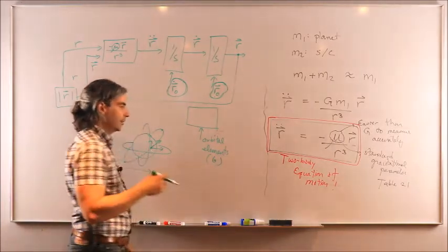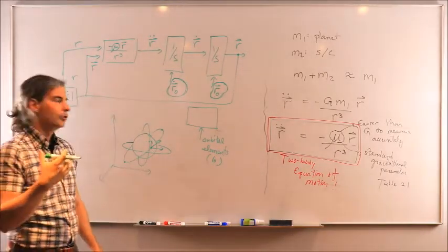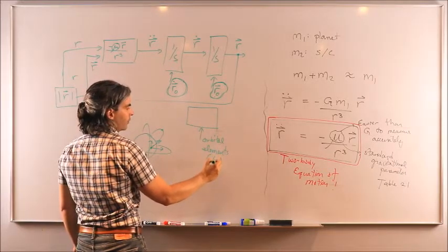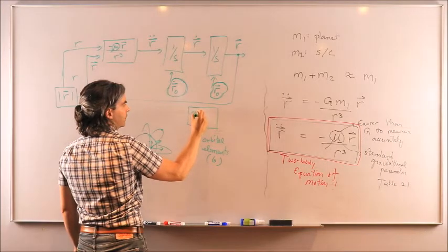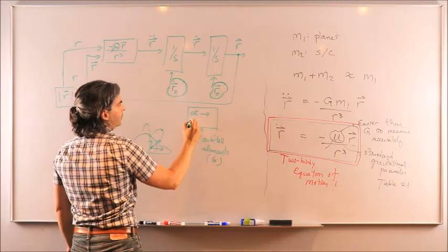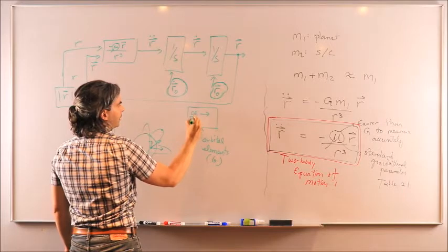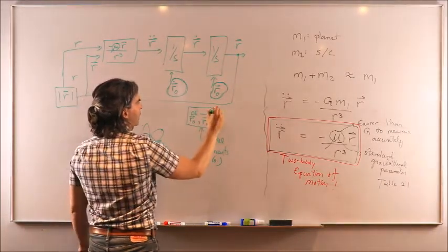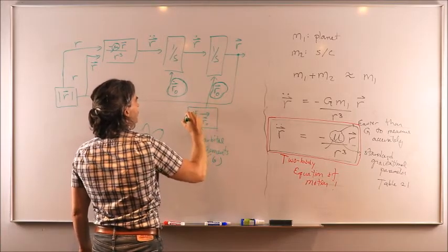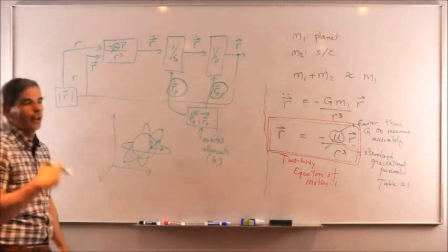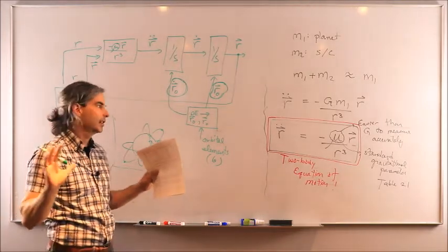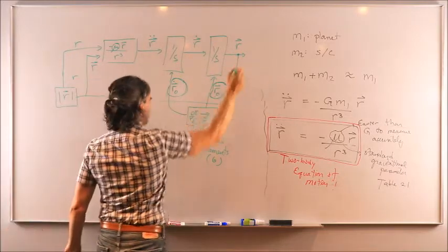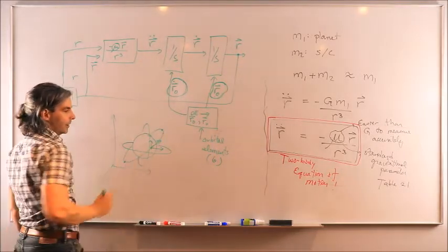Based on those 6 orbital elements that you would specify, there will be a routine that would allow you to convert from orbital elements, OE, up to initial velocity at t equals 0 and initial position at t equals 0. And then you feed those two signals to your integrator blocks, and then you start the integration process. That's a hands-off process at that point. It's closed loop, so it would generate the position x, y, z of your spacecraft at each time step.